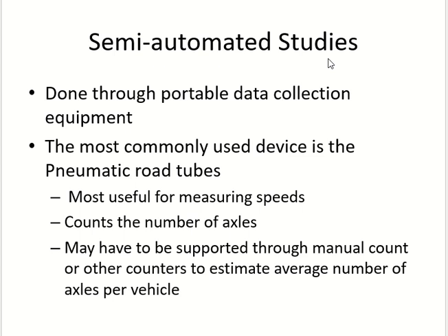A stopwatch is portable or not? Yes, right? So if you do a study with a stopwatch, is it semi-automated or manual? Manual. Why? Portable device, right? As I use my hand. So only having a portable device is not enough for semi-automated studies. It must be a portable device which records the data automatically. In semi-automated studies, we use portable devices which can record the data automatically. In manual studies, you can use a portable device, no problem, but we will not call it semi-automated.